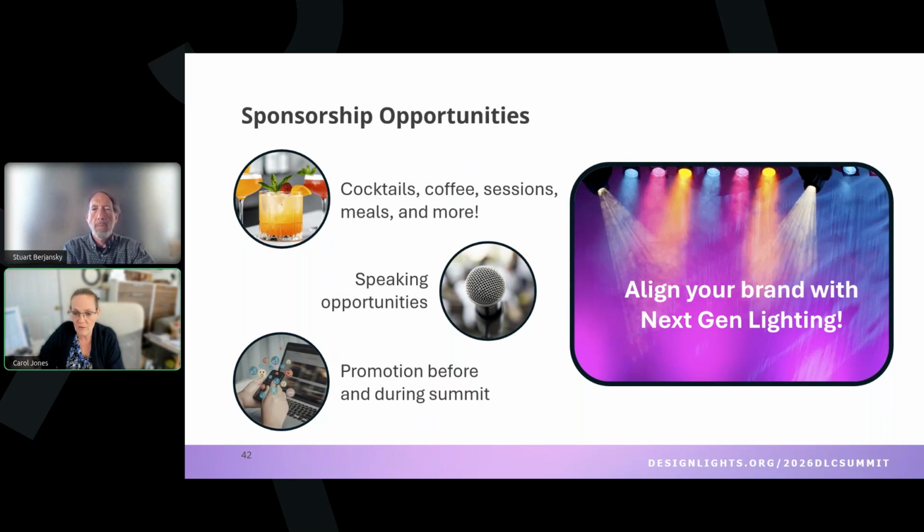If you want to have color tuning that's consistent, so you don't see yellow and green all over the place, DT8 is the way to go. If you are interested in having lighting, so AI, do you want AI or not? Do you want the data from your lighting system to be usable in AI applications with the rest of the integration of the building, because that is happening. It's happening fast. Lighting is either in the room or not in the room. It's either an opportunity or it's not an opportunity. If you go with analog 0 to 10, it's not an opportunity. There's no discussion, there's no communication, so it's just off the table.